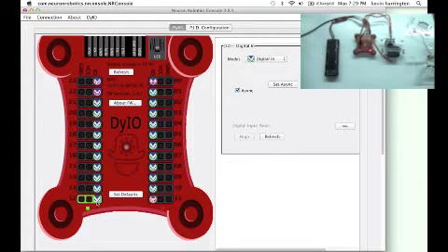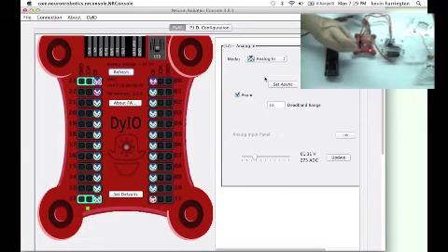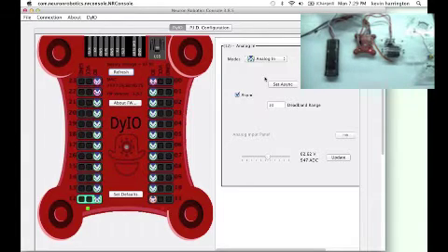The other mode you can use the PID controller for is with an analog input and a servo output. For this one, we're going to set channel 12 to analog input and then plug in our analog sensor. Note, signal always goes closest to the bowler hat, and we can observe on the screen the analog value moving.